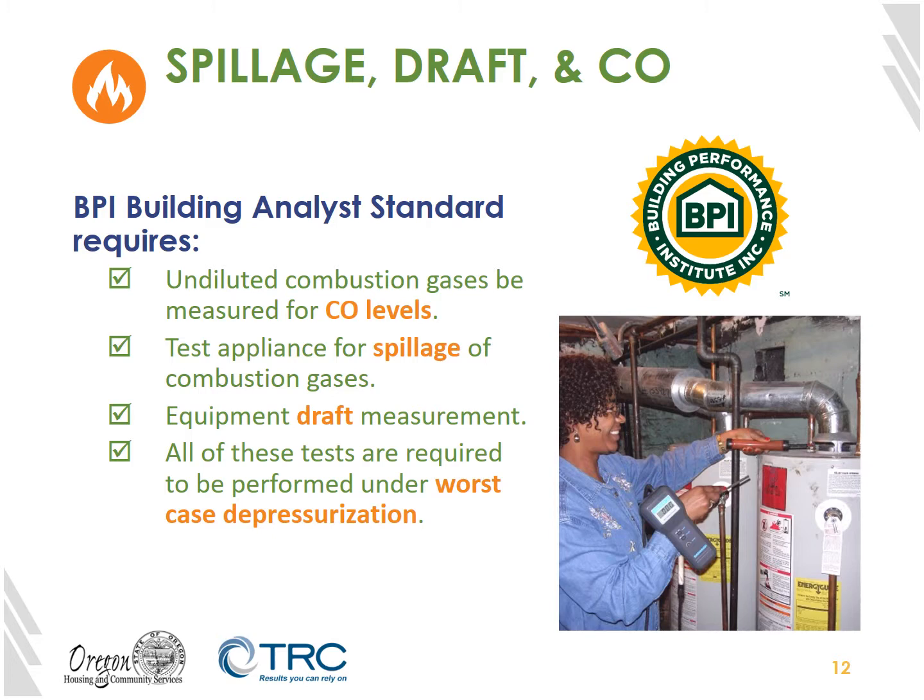And finally, all of these tests should be performed under worst-case depressurization, meaning you turn on as many exhaust fans as you have in the space in order to depressurize the room, the home, the apartment, or the particular space that you're in, to present the worst possible scenario that that combustion appliance would face and still be able to draft properly.